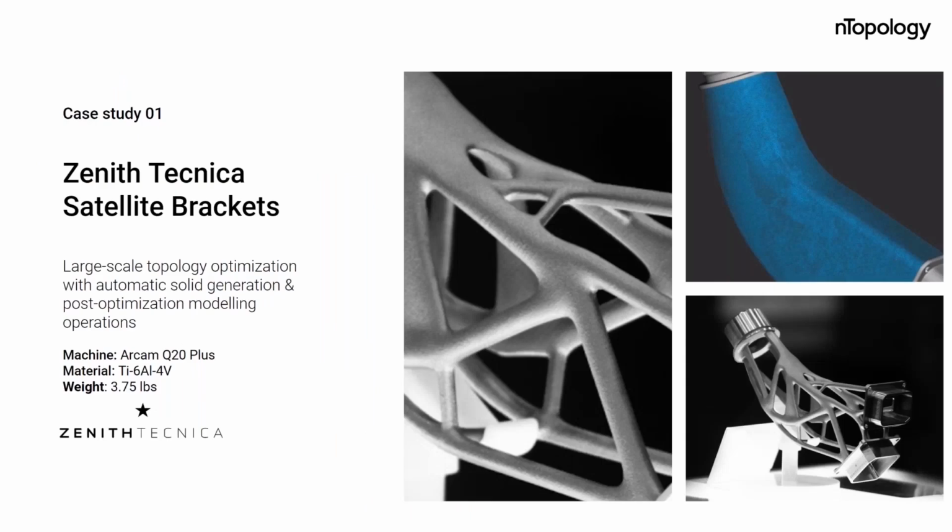And essentially here, what's nice about this is you can set up the topology optimization process, and because our model can read in that field directly from the topology optimizer in nTop, we actually can automate the generation of the geometry. You don't have to go in and model all of these little beams. Now, there's also a process where you can validate the part afterwards. And in this model, the optimization was actually missing a few beams that, for reliability, the engineer who was working on this was like, oh, I want to add a couple of beams here.